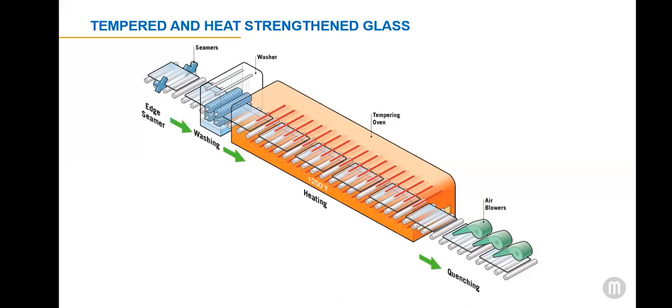Chemically strengthened glass has little or no warp, optical distortion, or strain pattern. This differs from tempered glass, in which slender pieces can be significantly bowed. Also, unlike tempered glass, chemically strengthened glass can be cut after strengthening, but it loses its added strength in the region about 1 inch from the cut. Similarly, when chemically strengthened glass is deeply scratched, this area loses its strength as well.